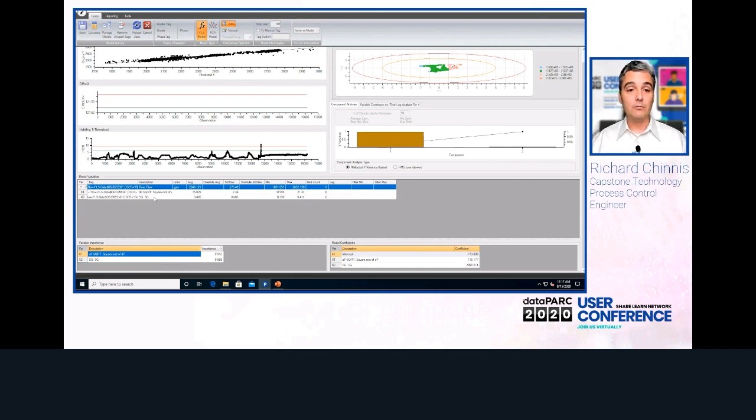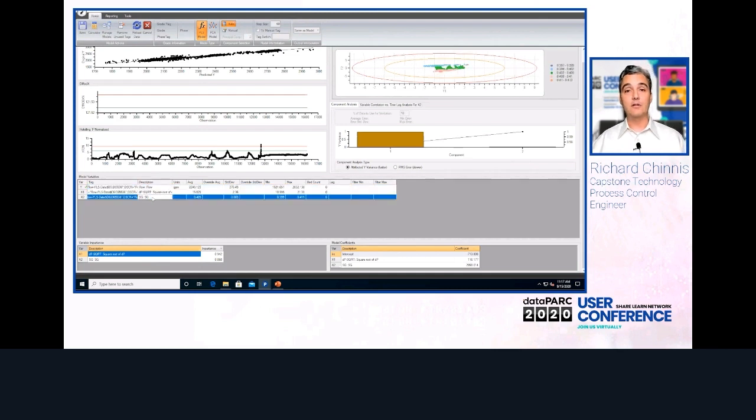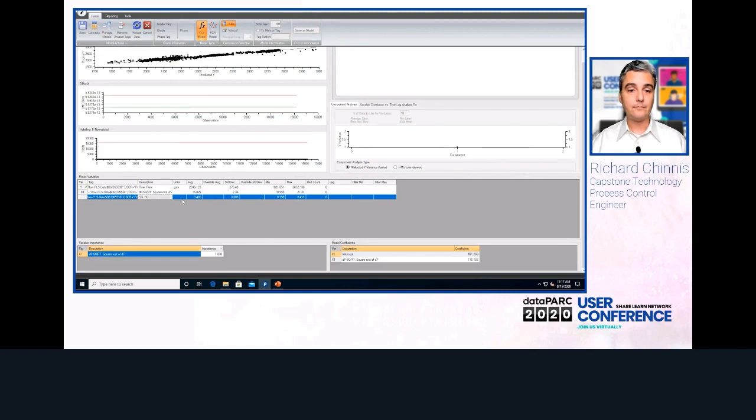So I have an opportunity to simplify my model. Yes, the model's good, but if I can simplify it, it may make it a little bit faster. So I'm going to right-click on this specific gravity right here, you see this x2, and I'm going to exclude the variable. Now you can see why I had the variable in there in the first place.